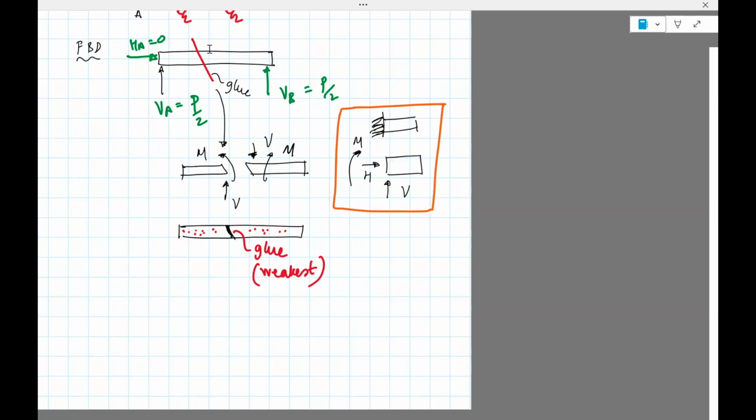Okay, so the shear force and the bending moment appear in the beam as we chop it off and look at it with the tools we've developed so far: free body diagrams and reaction forces. So in this section, we are going to compute V and M for a beam. This V and M I've shown you for one section, but you can do it for many chops all along the beam, and you can find V and M. You'll see that V and M changes as you go along the beam.